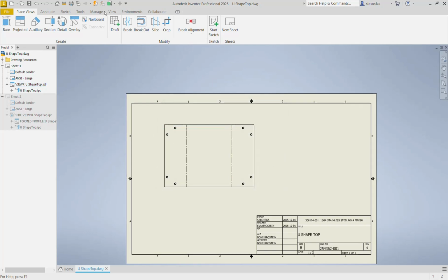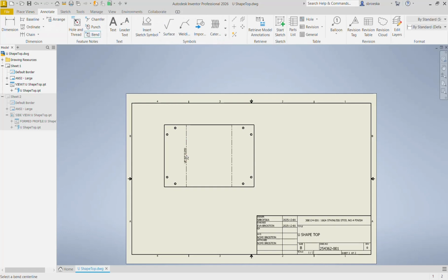Now I'll make all my dimensions and I'll give the bend, and now it says up 90. So that would be proper. So I recommend putting your bend lines on first, changing your views, and then naming them and giving it dimensions. Otherwise, you end up doing a whole lot of duplicated work. We'll see you in the next video.